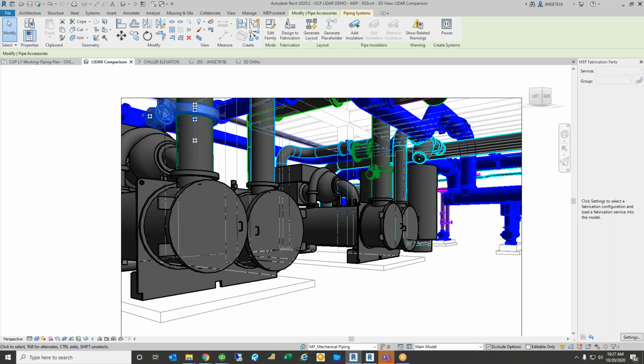That's hard to say, and the AIA has actually not defined what the dimensional accuracy of that is. What they basically say is once you get to LOD 350, you are at fabrication level accuracies. That's kind of the generic term that they use. LOD 300 is not considered fabrication level accuracy in terms of location and routing of piping, conduit, ductwork, et cetera, and the dimensions of the hardware.